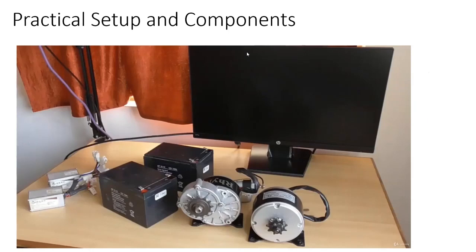Now let's talk about the setup. What setup have I got? Always I look at the setups, like these are the batteries of 12 volts each. If you connect them in series, 12 plus 12 becomes 24 volts. Okay, it becomes 24 volts, and amps remain the same. Let us say it has got 5 amps each. So 5 amps will flow at the output.